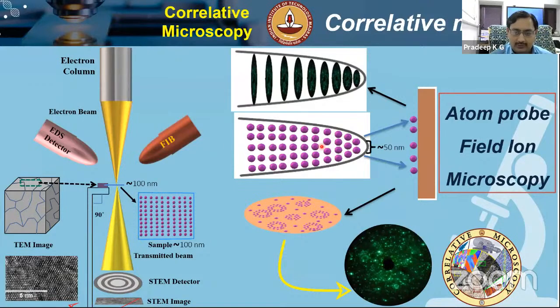Whenever people wanted to study hydrogen-induced effects like embrittlement in steel or other materials, the easiest way to deal with it right now is charging deuterium instead of hydrogen. And then the charged deuterium, if we can retain it in the material, probably accumulates at the defect sites, and those species of deuterium we can detect.